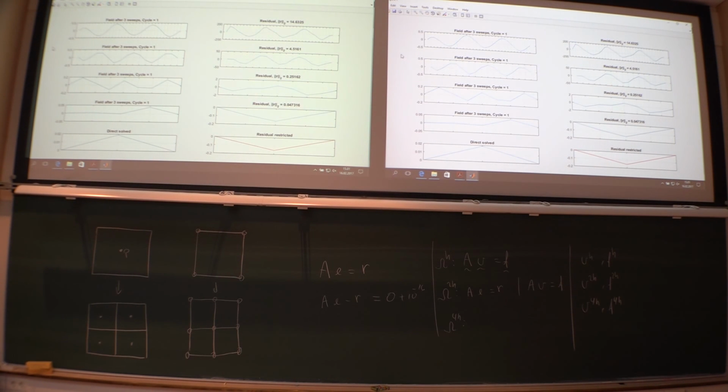Okay, back here we have the correct solution on the coarsest mesh. So now we are taking this solution and adjusting whatever we had up here. So that's the adjustment. Didn't adjust so much, but a little bit. And remember, here it's impossible to look at the physics in the problem, because you have the residual equation of the residual equation of the residual equation many times. So it doesn't make sense physically. Also, don't try to understand what the numbers mean. That's not the point. It's only on the fine level that we can actually understand what's going on.